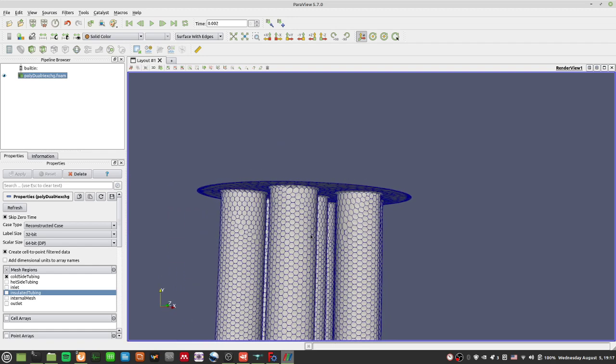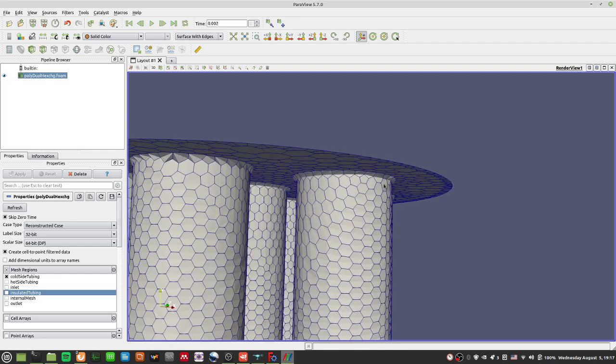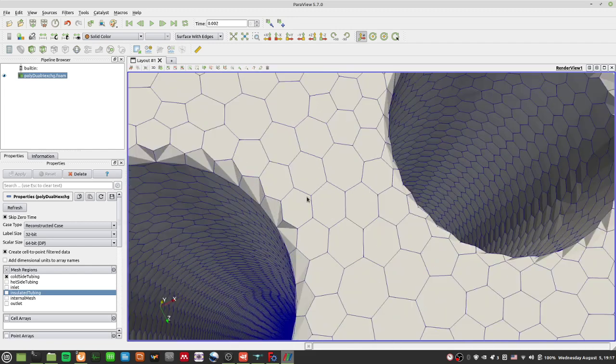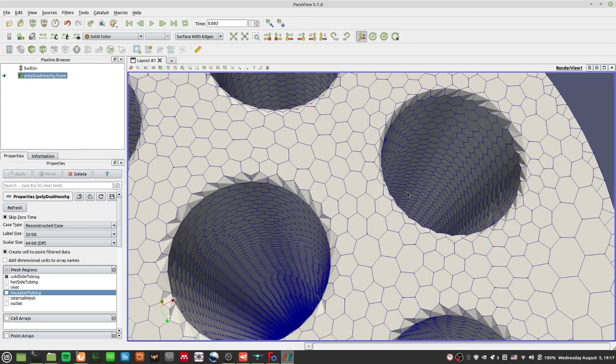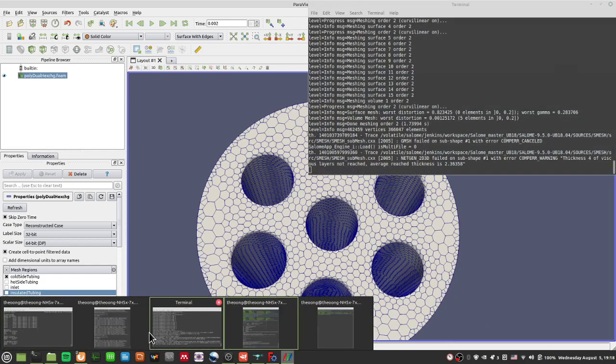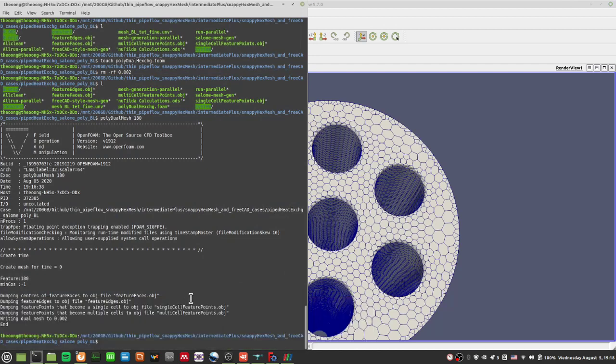Okay, so of course in FreeCAD you can actually make some adjustments over here to chamfer or what have you, to make the angle much smoother, much easier to accommodate. But that's another video for another time. Okay, this doesn't really affect the rest of the mesh too much. It just affects the sharp bends and corners. So that's what feature angle is about. If you do polyDualMesh at 120, you will more or less get the same result.